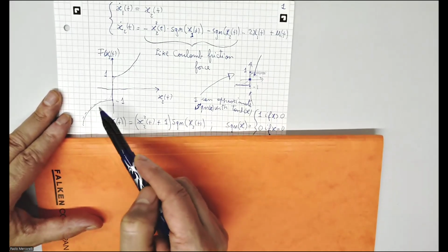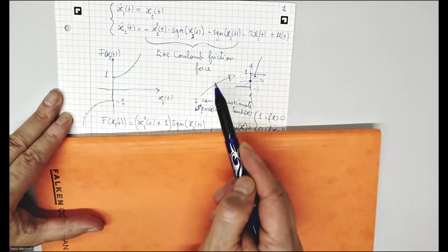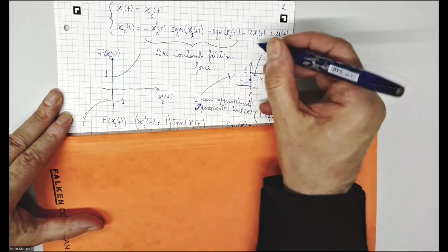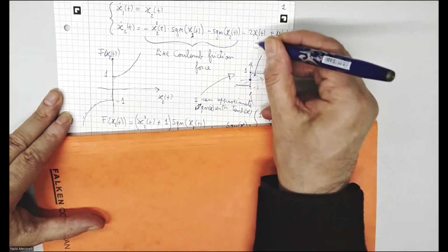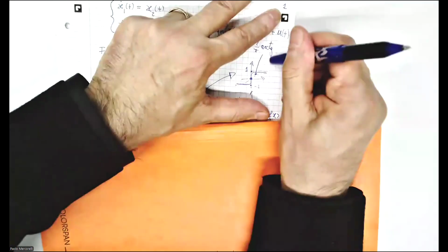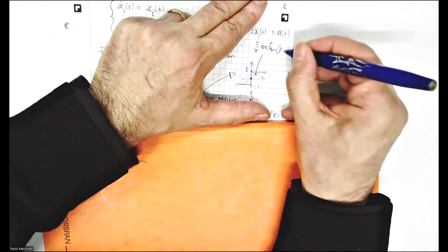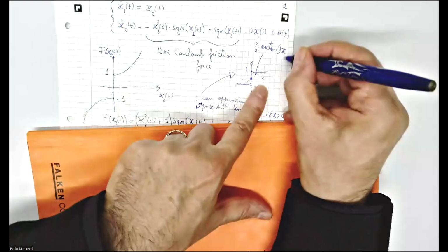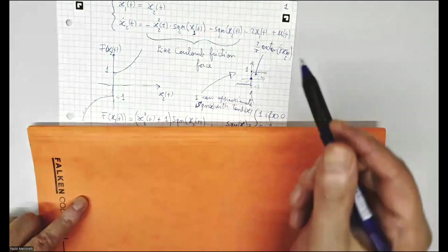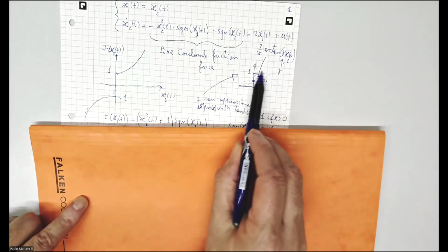It seems to me, I'm not an expert, but typically we approximate also this Coulombian friction with a continuous function. This could be, for instance, as I told you, arctan or arctg, I don't know which kind of notation you like. Here I put x2, I didn't put it, but gamma x2. And with this gamma, a constant, larger and larger gamma realizes a better and better approximation.